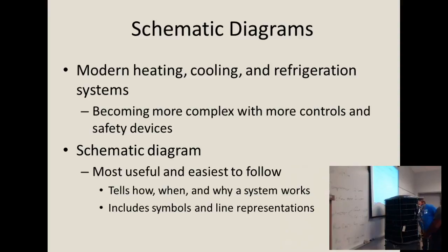Well, it disappeared on me. All right, what was that? 3? 4 want to come out of both of the capacitors and go to start. So what color is start here? Brown. What color is start here? Blue. So that one's going to go to that other side of the capacitor. Does it have an end on it? Okay, good. That brown will go up there. We said that was brown. We said that was blue. The opposite side, that's right. It's got to go through it.